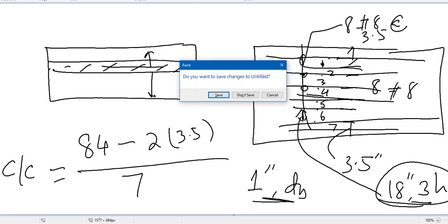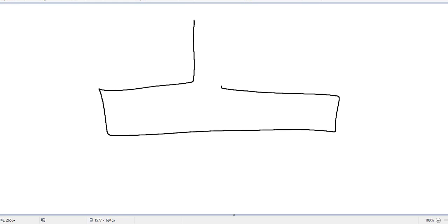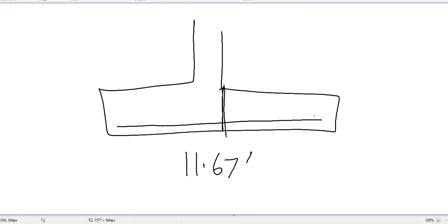So our footing is this. You say this is our long side, the long size in feet. Now our maximum moment is here. So when we provide our reinforcement here, we should make sure that we have at least the development length, so that the anchoring force here is developed to carry the force here.